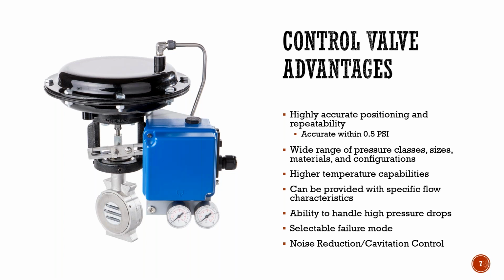So you can select fail open, fail close, fail last, and that can be on failure of air or failure of electric, but you can select the failure mode. And in a lot of cases, you can choose to have noise reduction or noise mitigation and some type of cavitation control as part of the control valve as well.